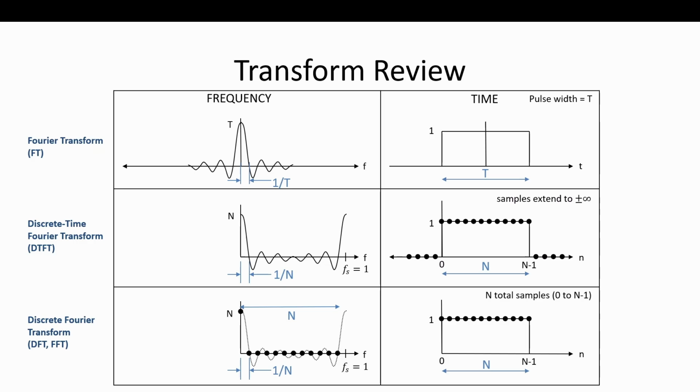That's a big thing to keep in mind, because that's where that thing I said was a rookie mistake in terms of the filter design comes from. You think, oh, it's all zeros. It's great. It's perfect. It's 1. I'm going to define that to be my frequency response. What you're not realizing is this is the frequency response, and see the ripples that are there? They're here as well, because if you take this and look at the frequency response of that, it will reveal those ripples that are in between. You're only seeing part of it, because it's discrete.